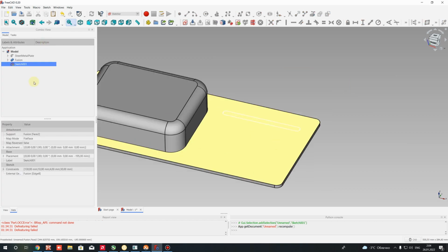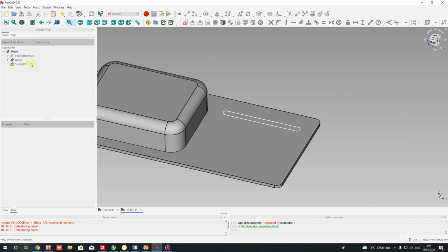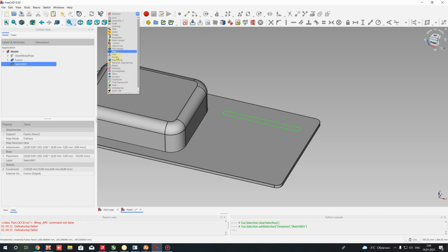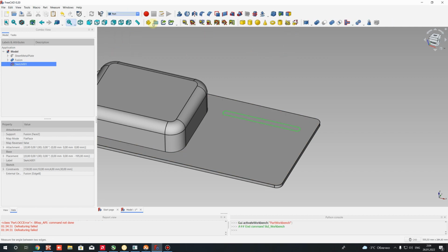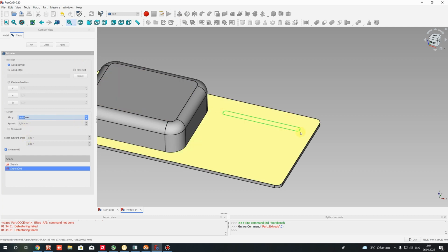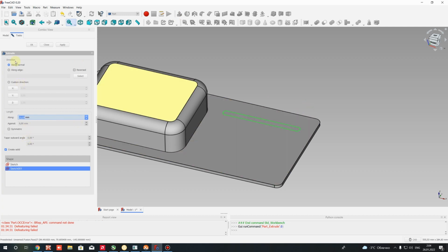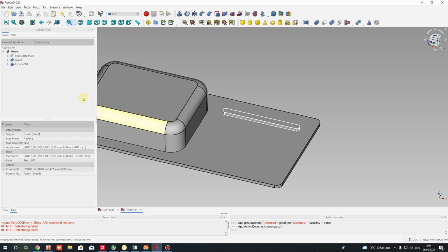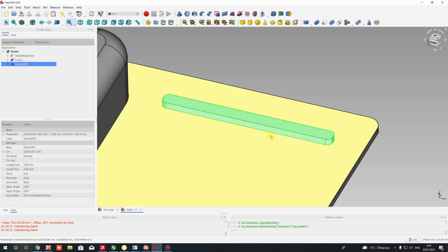close the sketch. And now for the sketch, let's make the extrusion operation in the Part workbench. Let's go to the Part workbench again, choose the sketch and make extrusion. Extrude it, use this icon. We have to choose this sketch here, and now let's set the length of extrusion. I think 5 millimeters. Let's set it. You can use another value, it's what you want, but for this tutorial I'll use 5 millimeters here.